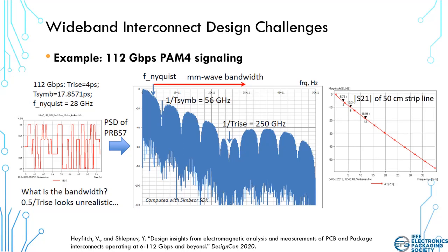Here, the goal is to then design channels and even integrated circuits themselves to accommodate some portion of this bandwidth. And here we need to then choose some cutoff and determine what happens on the transmission line at all frequencies up from DC all the way to the band edge. So your design goal could be insertion loss, it could be return loss for a shorter line, it could be anything you like, as long as it's relevant to your signaling standard.